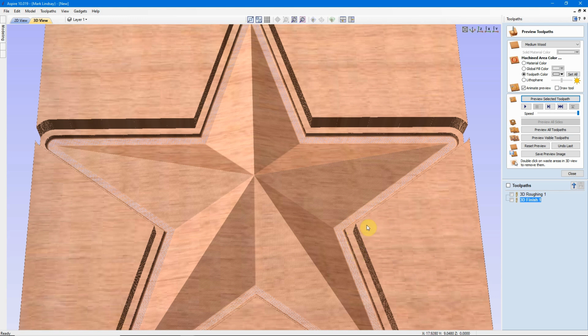Rather than cutting air from the material surface, I want it to start cutting about right here and maybe make a pass in the air. I don't know. It's just going to depend. It may cut all the way through. I may not need to do this profile toolpath, but I'm going to calculate one in case I need it. I need to remember negative 1.2, and I'm getting that number by looking at my readouts right down here. When I put my cursor right there, I can see it's negative 1.2.